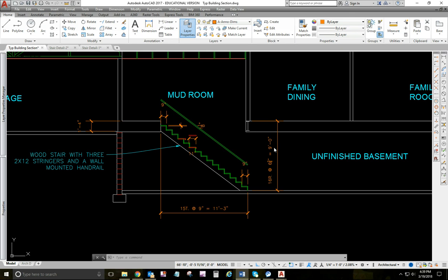And then I divide it by 16. It gives me 6.75 inches. I go both ways on it. I round up and I round down, divide both ways, and I can kind of see which way is going to be best. Okay, 7.2 inches is kind of tall for a riser height. It could work, depends on the situation. So we're just going to hang on to both of those numbers.